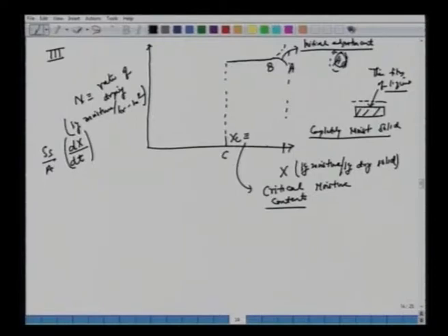If the moisture content is greater than xc, the rate is constant here. Why is the rate constant? Going back to our previous discussions of thin films of liquid, it's just like a constant rate of evaporation. Whether you're drying from a solid surface or you have a pool of liquid, it's all the same. Now after the critical moisture content, we can call this a constant rate.